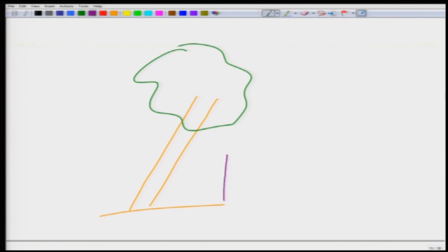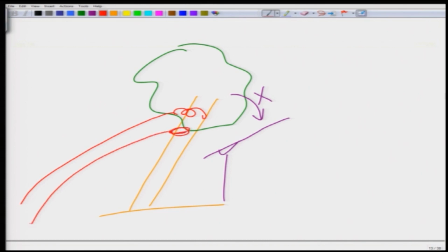probably you have an electrical line on this side. So, you do not want this tree to fall to this side, this is to be avoided. So, what you will do is you will attach ropes to this tree and you will start pulling it in the other direction, and then you will make your cuts, so that it does not fall in its leaning direction. But typically we prefer a tree to fall in its leaning direction.